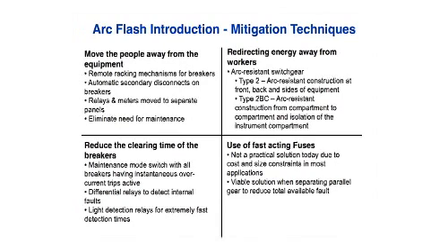All right, there are also mitigation options on retrofit, and let's talk a little bit about that. In retrofitting, there are several things you can do. One, you can put in arc mitigation relays, i.e. the REA, or other relays. I know that Schweitzer has an optical port on their relays, as does ABB. There is what I call a crowbar approach to arc mitigation. In other words, something that is sensing the fault, and then all of a sudden we just close a ground on the main bus and short the entire switchgear out instantaneously, or certainly within the first 3 to 5 cycles.